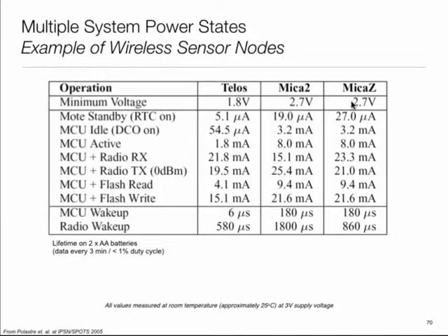If you were to look at the voltage of the battery as the battery dies, what happens? It goes down. Voltage goes down. So now this guy is going to die sooner, because as the voltage starts going down, there's very little margin out here. In fact, AA is more like 1.4 or something, so it actually has very little margin, whereas this guy can keep going down quite a bit. So you can extract more battery life out of this because of the lower voltage property.